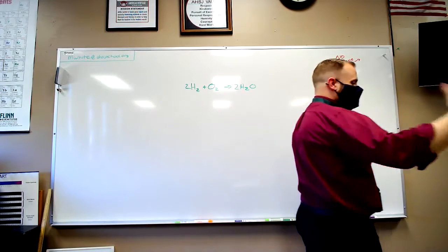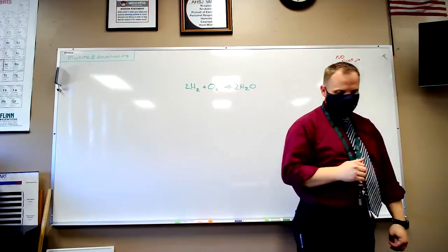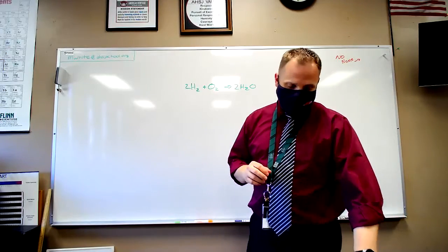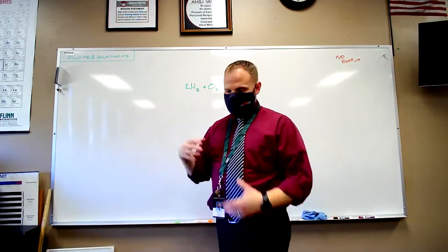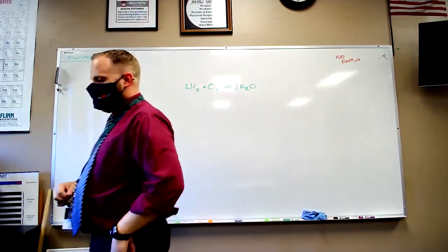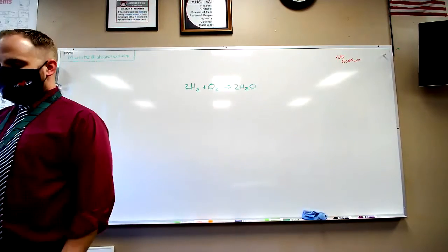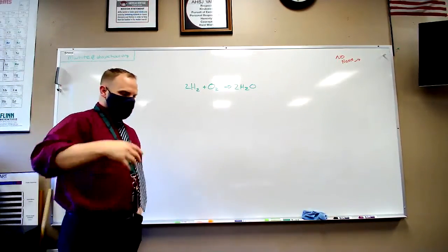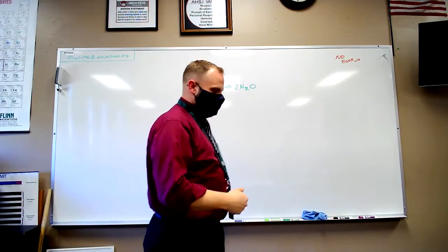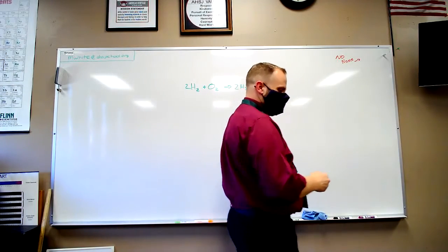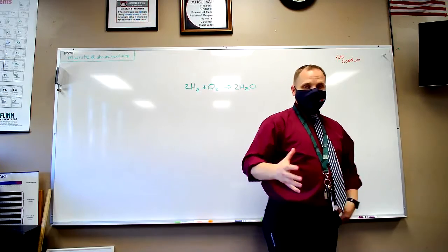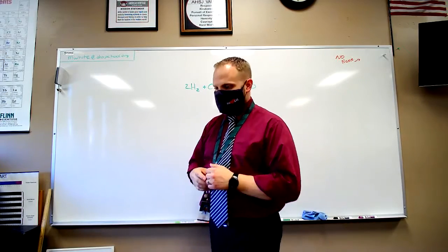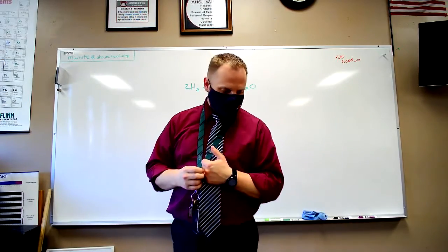Now they do get used up in this process. That's why they're called sacrificial, because we're sacrificing them. But we would rather keep replacing these blocks in order to prevent the hull of the ship from rusting away.